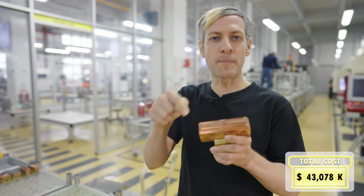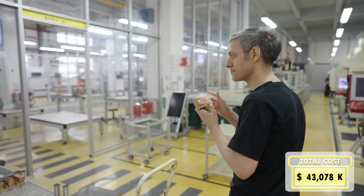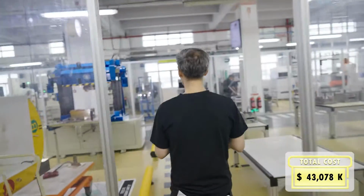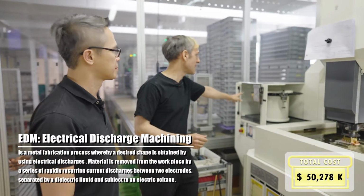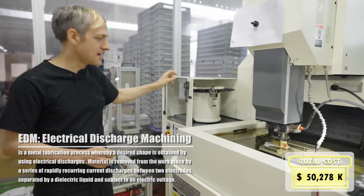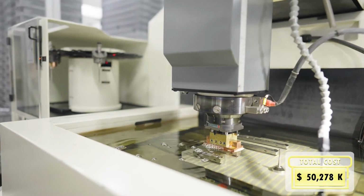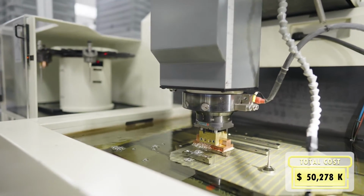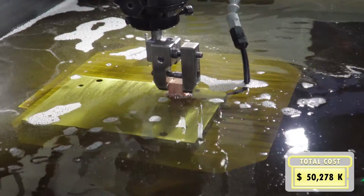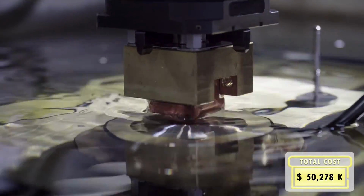After the copper block is finished, they place it into this magazine, and they can load the machine up with different shapes that it will use, and then it brings the copper block over through a special process that we call EDM, which stands for electric discharge machining. And this system is very accurate.